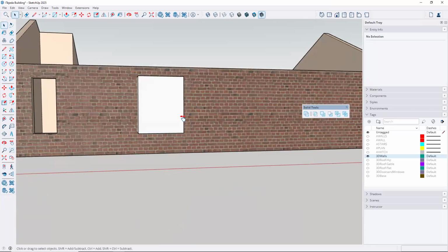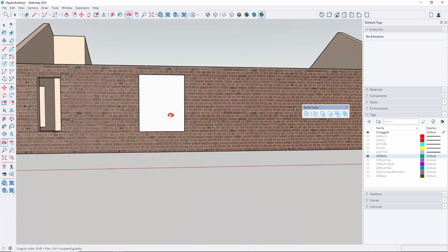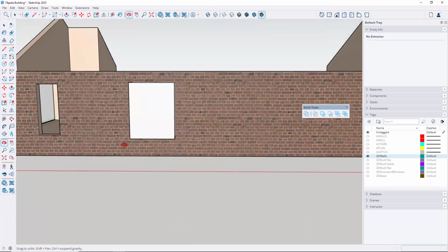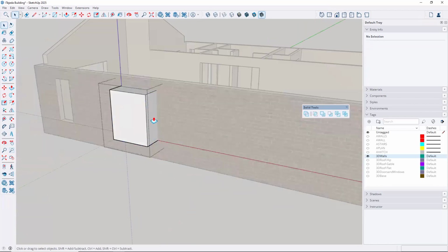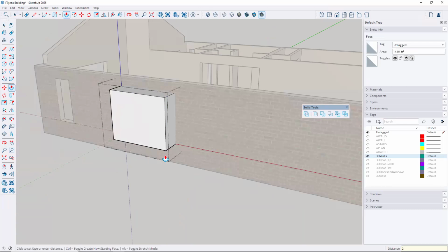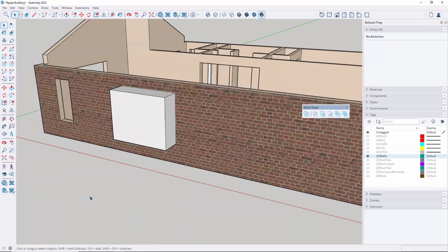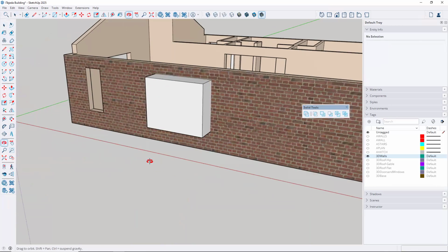And you can kind of study and go, okay, that's where the opening is going to be. What does that look like? Maybe I want to make my window a little bit wider. Okay, double click on that solid. P for push pull on this side. I'll bring it out 2 more feet like that. Tap the space bar, click away from that group. And that's where I want the opening.